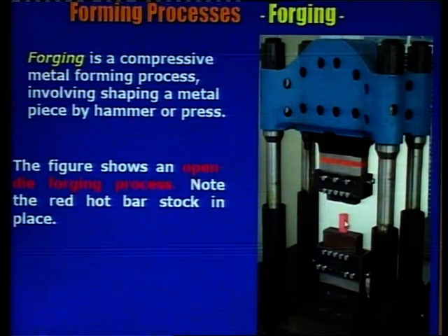This one is called open die forging, and the shape of the material is not controlled. It can expand freely. The height will decrease and the diameter will increase. It may not remain circular, although because the pressure is uniform on the billet, the diameter is likely to remain the same and the shape is likely to remain uniform or round, but there is no guarantee.